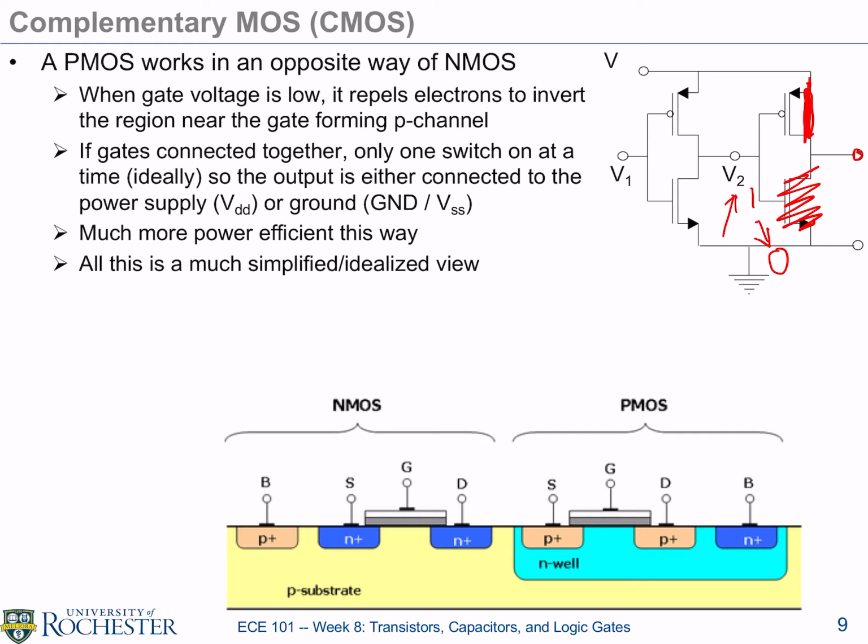This does exist, but in the steady state, not in the transient. In steady state, with CMOS, we don't have a conducting path. Okay, this is again an oversimplification. If you look at how the threshold works, there is the sub-threshold leakage, there is a gate leakage, there's some leakage, but the intrinsic steady state mode is that there is no current in steady state. So that's a good thing.